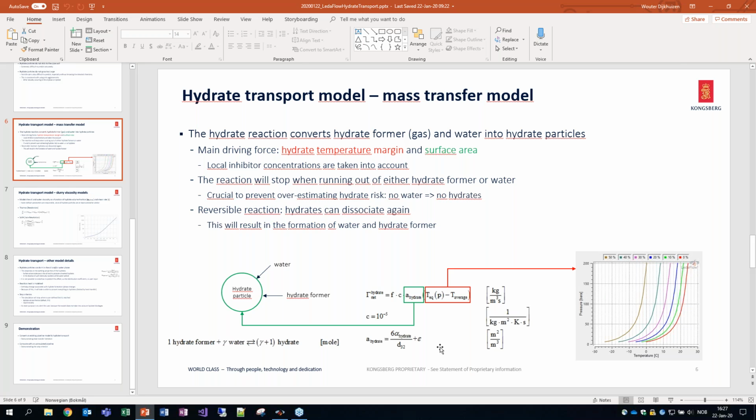So if you have a certain kind of oil, then you will end up in one situation, or maybe with gas condensates you will end up in the other situation. So you can't really design that. Yeah, so you need to do simulation. And then whether or not the hydrates end up in the oil or the water phase, you can determine that in the lab.